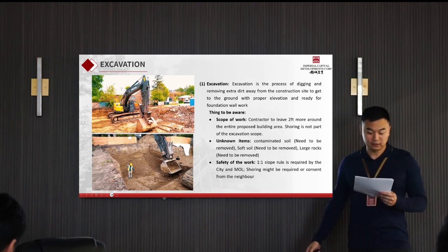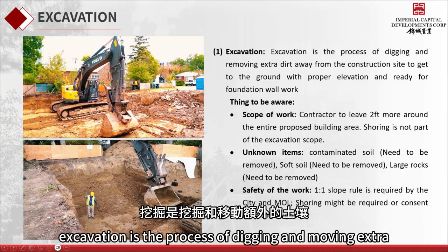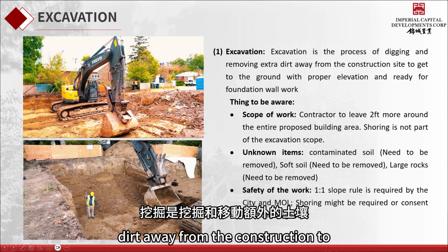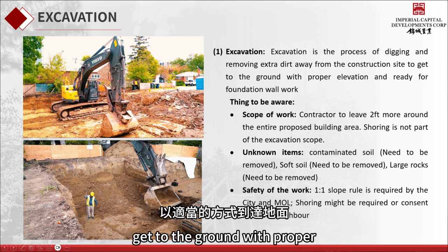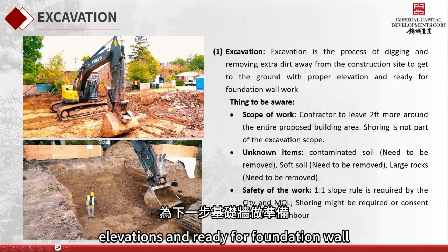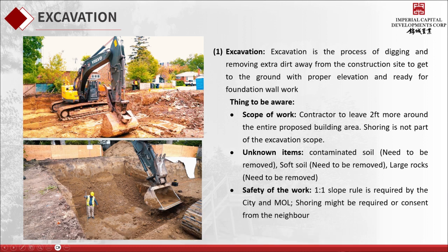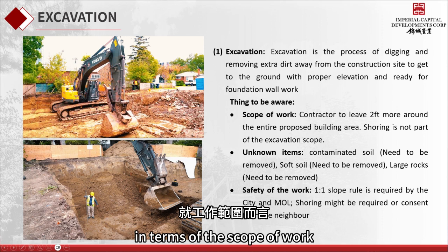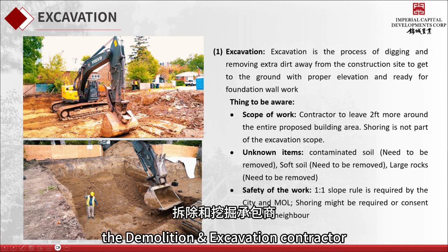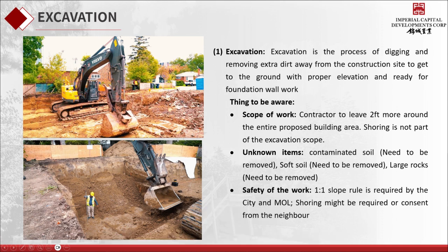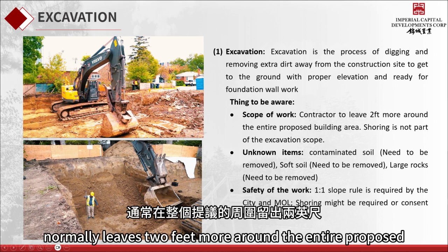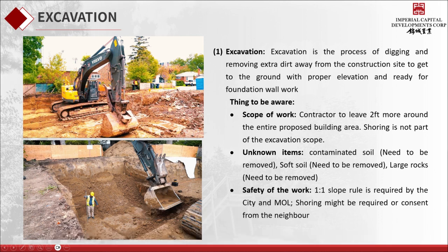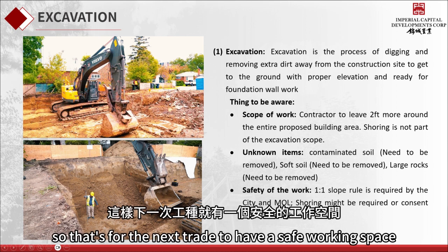Excavation. Excavation is the process of digging and removing extra dirt away from the construction to get to the ground with proper elevations and ready for foundation wall work. Things to be aware of, in terms of the scope of work: the demolition excavation contractor normally leaves 2 feet more around the entire proposed building area. That's for the foundation, for the next trade to have a safe working space.